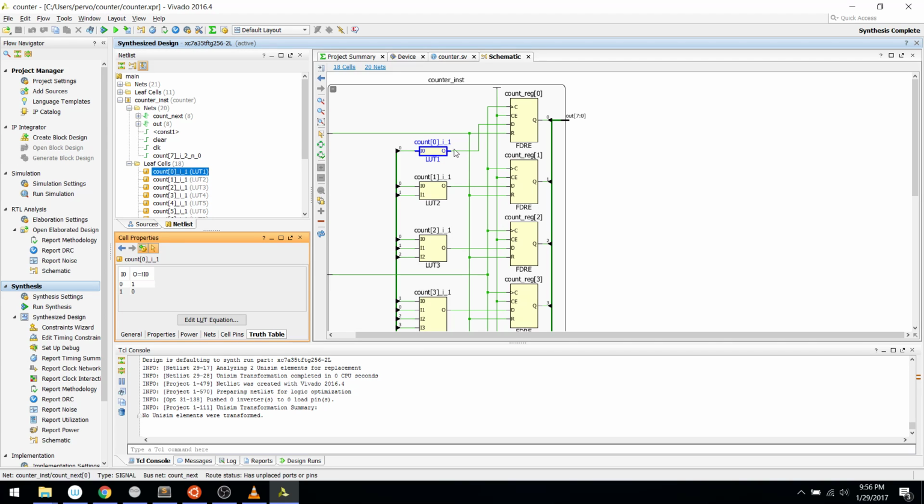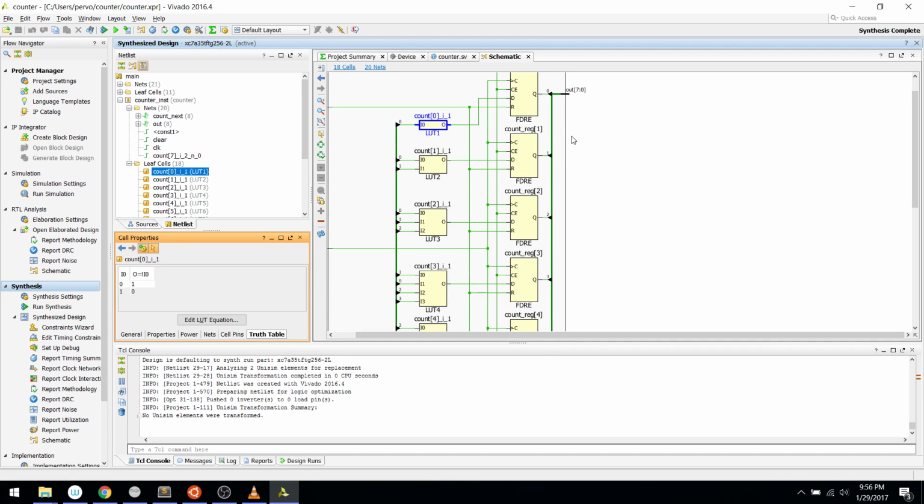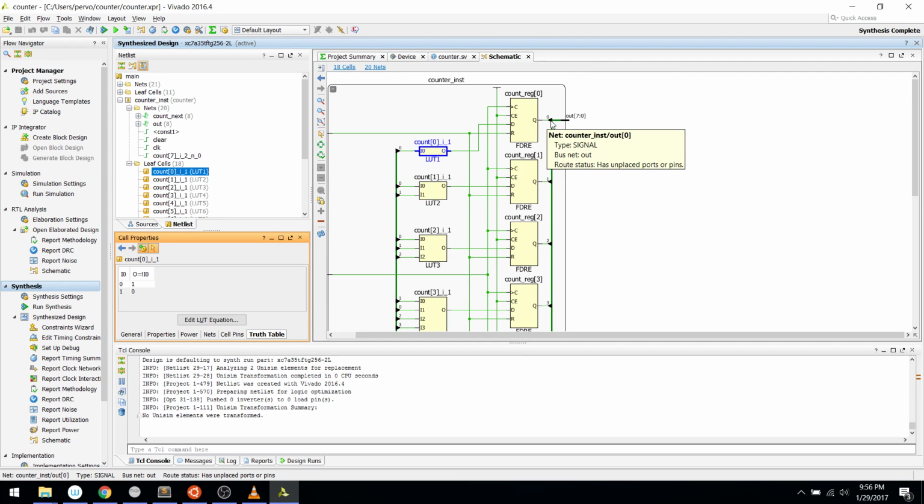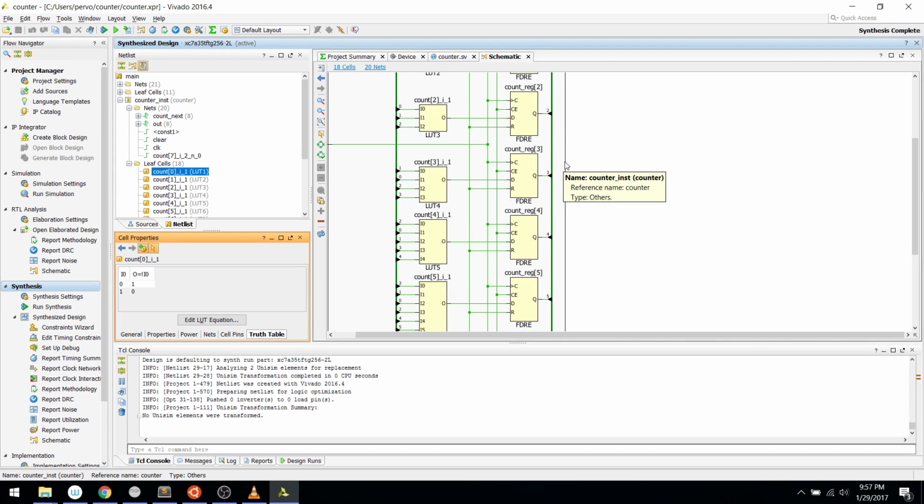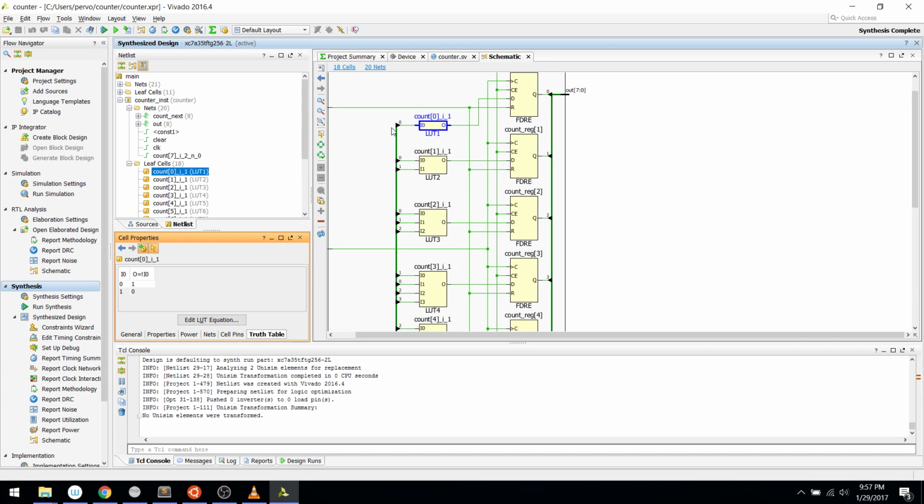And so based on that, and given that this specifies the new value of the first bit of the counter, you'd expect the input here to be the previous bit 0, or previously significant bit. And indeed, that's what is going on. I'll explain this schematic notation. Even though these FDREs are actually individual bits, there's this way where you can kind of gang them up together into a conceptual vector of them. So that's what this fat line with the triangle and the indices means. It basically means that the Q of this top one, count reg 0, becomes the index 0 of this vector net, and so on. And then on the input side, you can see this one selects the 0 component and feeds it in. So indeed, this does the inverter.